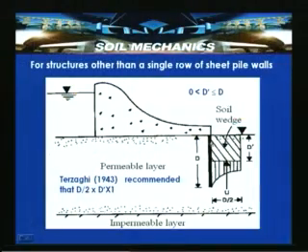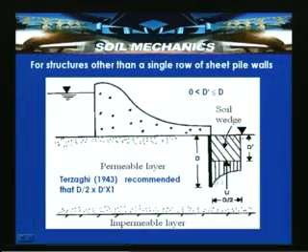In such situations, for a masonry pier with a cutoff sheet pile wall here, according to Terzaghi in 1943, d' is the zone of the possible soil wedge or possible failure zone, and this is the zone where the uplift exists. Using a similar procedure, he approximated d/2, that is this width, and d'. So the d' value was said to be 0 to d.